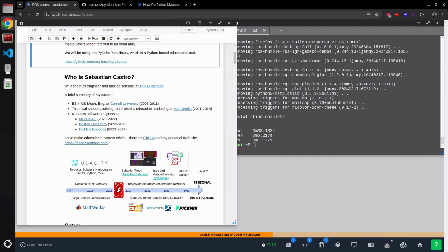These tools are very good for getting something working and talking to a robot. Even if you've seen the talks we've gone through today, we haven't needed to worry very much about how the actual algorithms are implemented. And I think that's a good thing. I think it's great that with all these ROS tools, you can grab your EKF package and have something working with only configuration files. That's a big power of ROS.